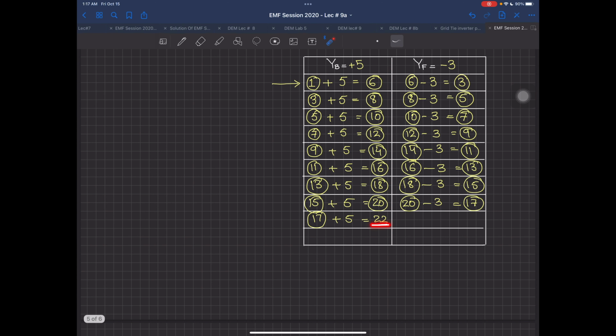Now if you are talking about 22 over there, this means that you will count up till 20, and then after 20, because this is a circular slot numbering, for the 21st I will call it again slot number 1. For 22 I will again call it slot number 2. So practically, over here I am going to call it 22, but it will actually be the second slot, because this is the whole symmetry.